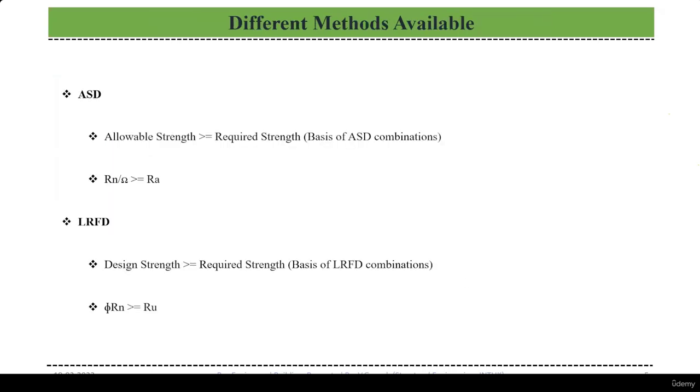Next, the different methodologies available according to these codes. One is ASD and the other is LRFD. I think we have in Indian codes the working stress method and the limit state method. Same as the working stress method, we have allowable stress design.